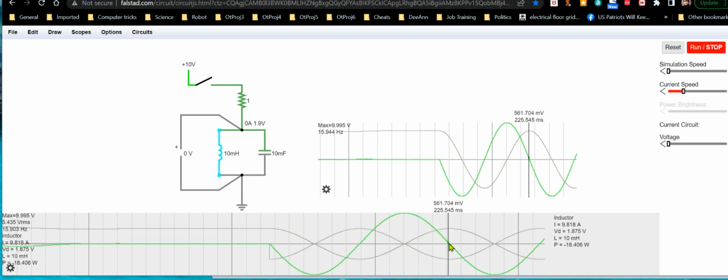Like I said, when the voltage reaches 0, that means the inductor is fully charged, and you see the current's maximum. So, when the capacitor is charging up, its current increases and its voltage falls right up until it runs out of juice, which means the inductor is fully charged at that point, which is peak current. And then, once the inductor is fully charged, it goes back into a discharge cycle, which starts out at the high current it left off at to try to resist its current changing, but that ends up dumping all its energy eventually into that capacitor, and the cycle keeps repeating.